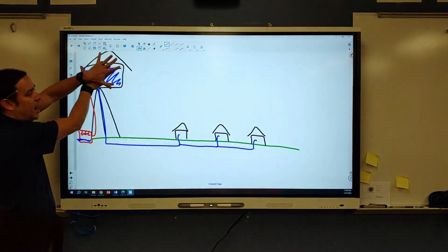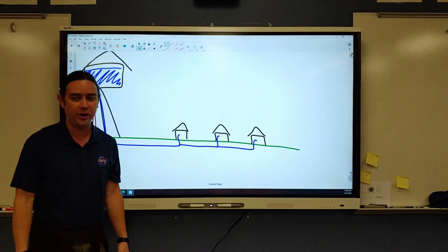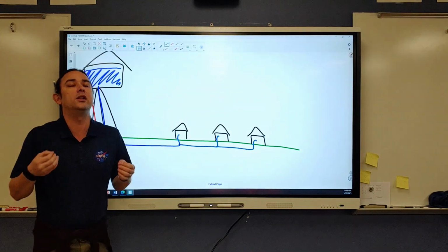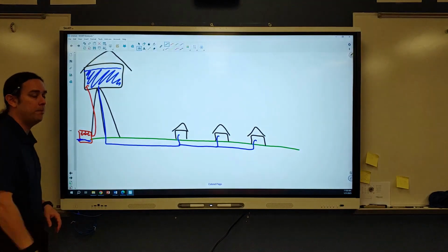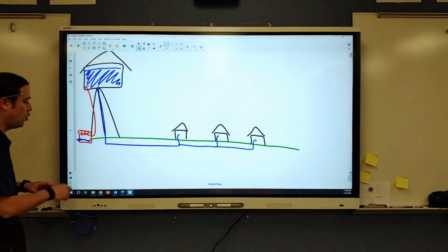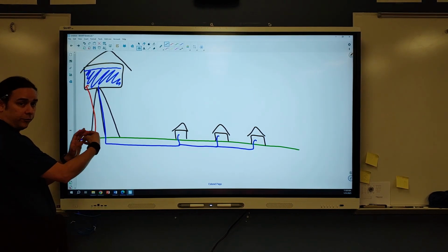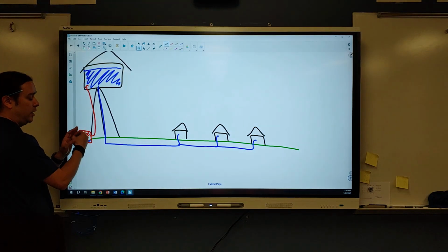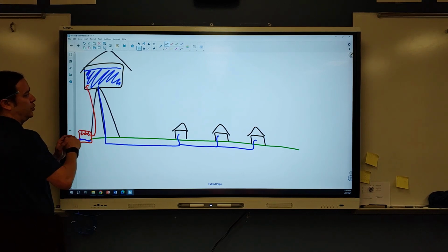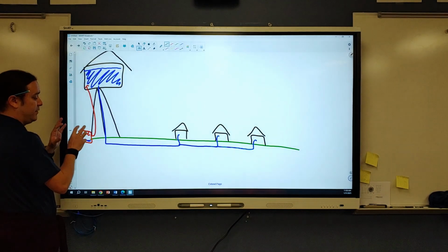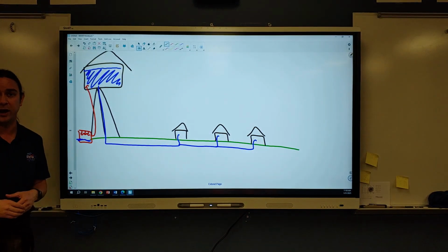If you didn't have a giant reservoir to pull from and you had a pump and everybody flushed the toilet at the same time, well then the water pressure would completely collapse, and faucets would stop running water, the toilets wouldn't refill, at least for a while, until the pump could get caught up on it. In short, you can take a lower power pump and have it just taking the water coming in from, say, a treatment plant, where it's nice and clean and ready to go, and it will put, I don't know, maybe a gallon every second up into the giant water tower. Instead of having a gigantic pump that needs to do 1,000 gallons per second so that everyone in the city would have the water they want.